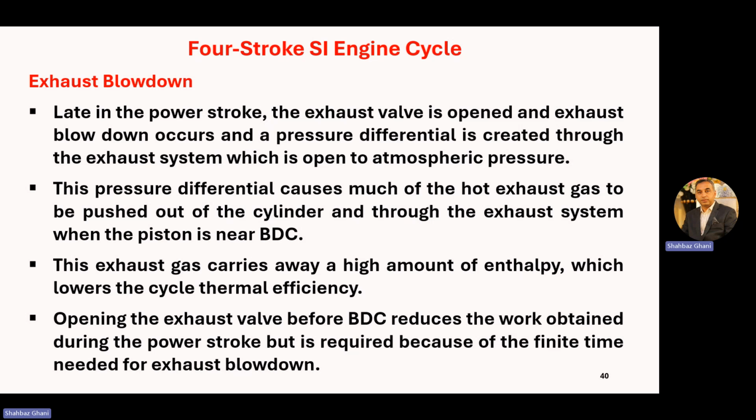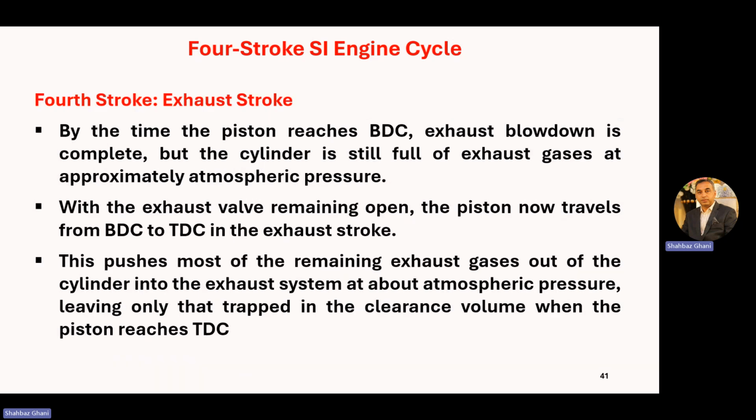But before the BDC, if we open the exhaust valve, the hot gases will leave the chamber and the pressure exerted on the piston top will be less. So there will be no difficulty in the exhaust stroke moving from BDC to TDC. So this exhaust blowdown is very, very essential in the four-stroke system.